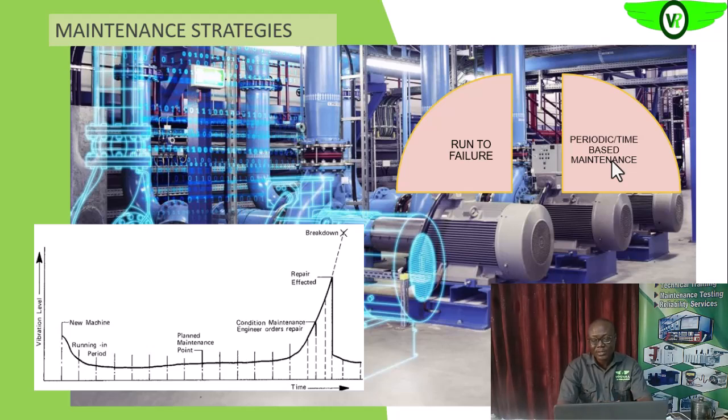Are we getting it? So, one, failure before the PM time for that particular component, which can result in other expenses. That will be as a result of other components failing alongside that particular component. Then if the component has some useful life, the remaining useful life will be wasted. So all of this put together will increase our maintenance cost or reduce our savings.